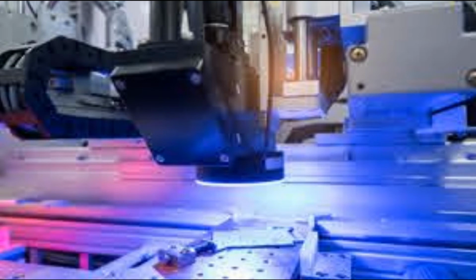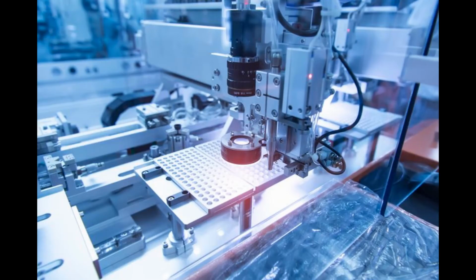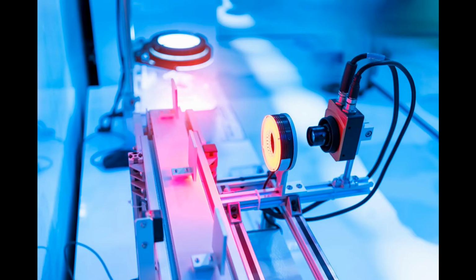In the case of an automatic inspection system, which are very common nowadays, we need to make sure that the cameras, in the case of a vision system, have the right resolution, that the software is properly built and doesn't have any bugs, and that it's reliable. So we need to test multiple times in extreme situations. We need to observe that the ambient light doesn't affect the results. This is very important for optical inspection systems.